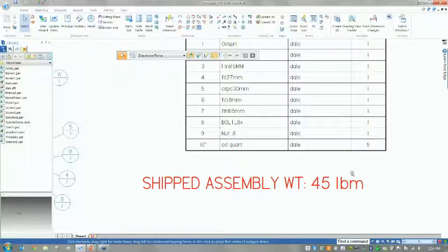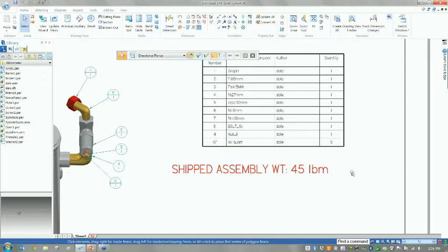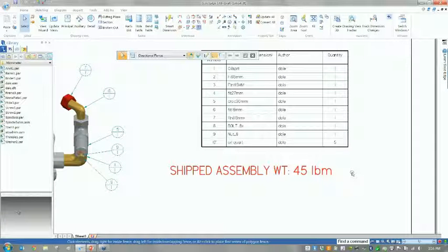It'd still be the same amount. So what we can do now is override that, put, say, 100 screws in, or 5 quarts of oil, and then actually have the weight reflect what's going on there. So this is our new override mass property that we have, and we can override it when we use the occurrence properties.